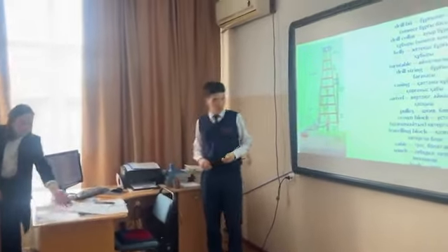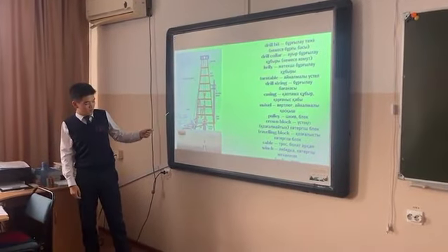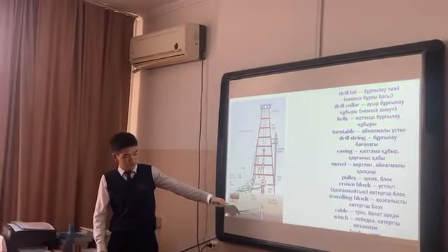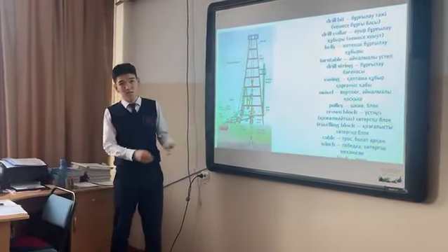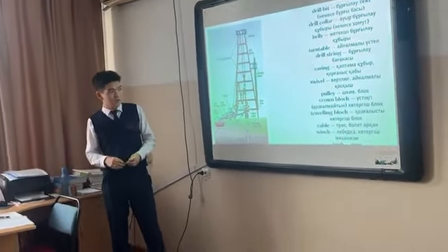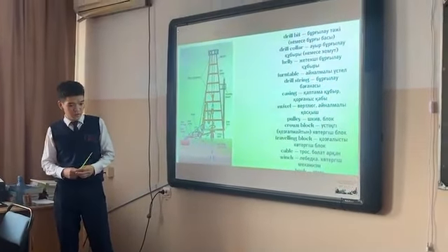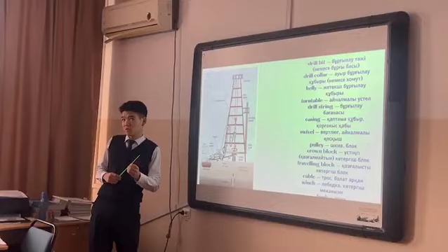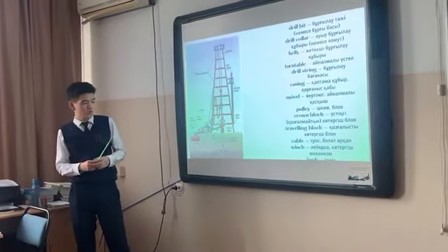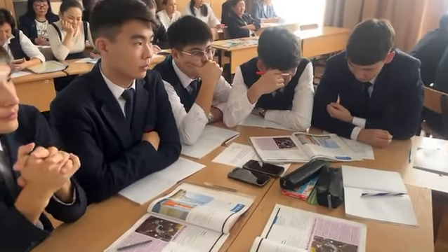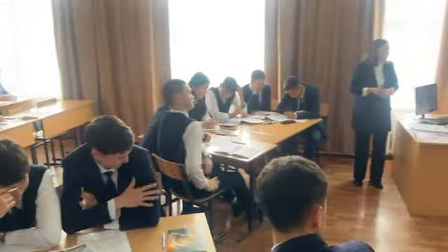The mud goes through with the help of the mud pump from the mud tank to the drill bit through the pipes, and the mud cools and cleans the drill bit, and after that the mud goes up with the rock cuttings to the mud screen to separate and use it again. Yes, go back to your seat. Okay, thank you.